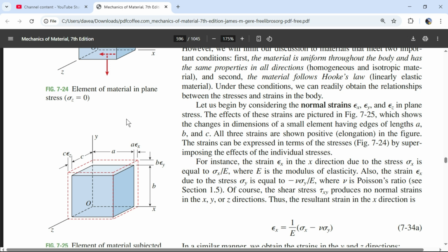And so we have this proportion. I can only lengthen, and you could think of that as a percent. If I had 1,000 and I can increase it to 1,002, then that was a percent increase of 0.2%. Except those numbers are just so small, it's really hard to wrap your mind around the percent increase at 0.2%. Like, I have a hard time, 0.2%, does that make sense? Not really. But the proportion is probably even worse, because you're taking 1,000 and multiplying it by 0.002 to get 2. You know what I mean? But any length multiplied by 0.002 for steel is going to give you the max change in length.